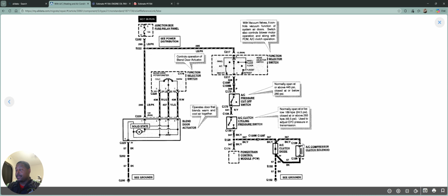As if my memory serves me right, that's what it looks like. Connector 106, it's a black and yellow wire. You should have 12 volts power going to that connection. And then on the other side, since this solenoid has used up all the energy, you expect to see 0 volts on the ground side, the black wire. This diode is here just to catch ripple in the system when the solenoid engages and disengages. Okay.